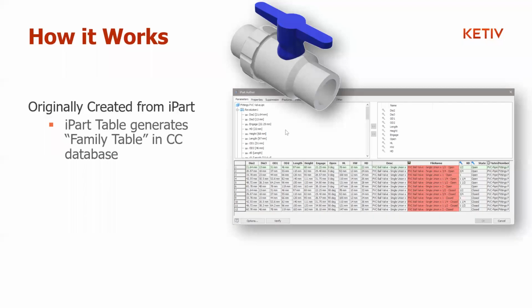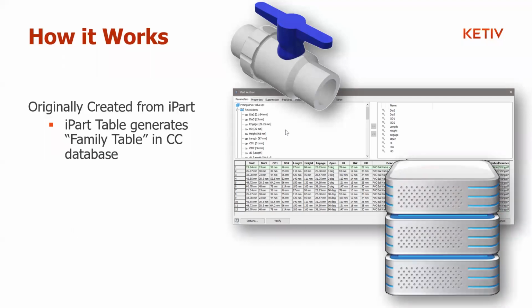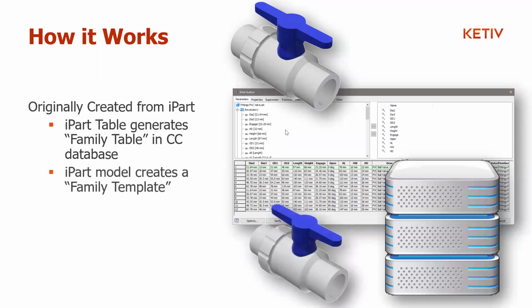So the way it works is, when you're working with an iPart, there's a table there, and it generates a family table in the Content Center database when you publish it there. So you just have to get it there. The iPart model that this starts off with creates what's called a family template. For every family of components, like a nut or bolt, there is one part that gets used.